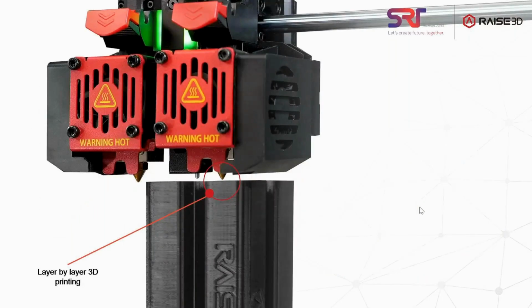So the technology of compounding and blending chopped fibers into the thermoplastic matrix was leveraged to make 3D printable filaments. And triple F 3D printing technology, or fused filament fabrication technology, is the additive manufacturing technology that enables the process of fabricating fiber reinforced thermoplastic parts.